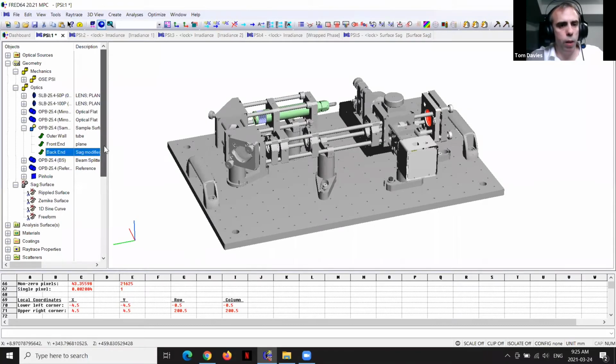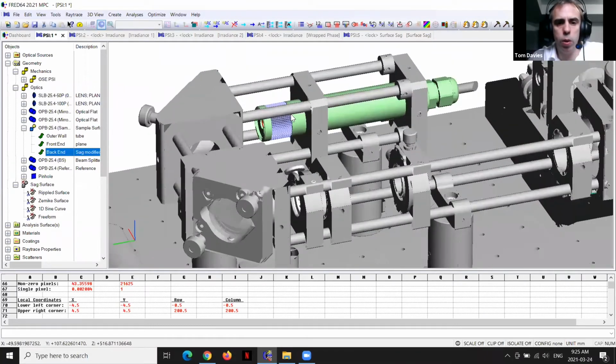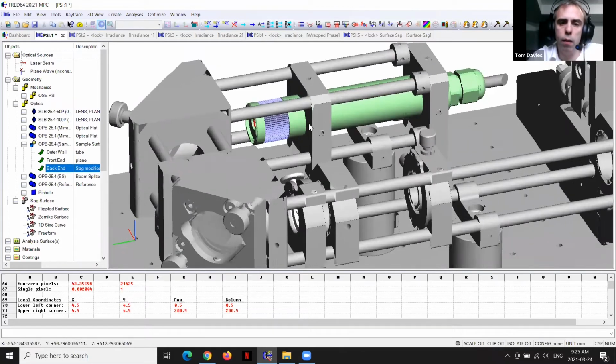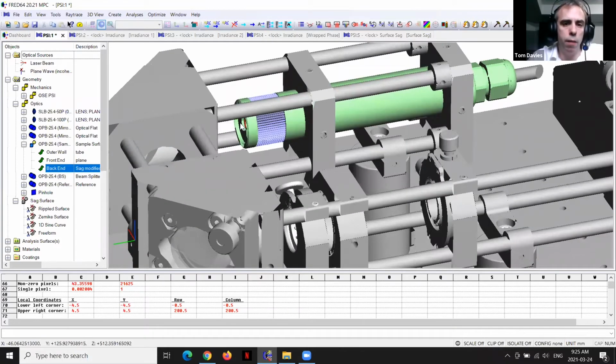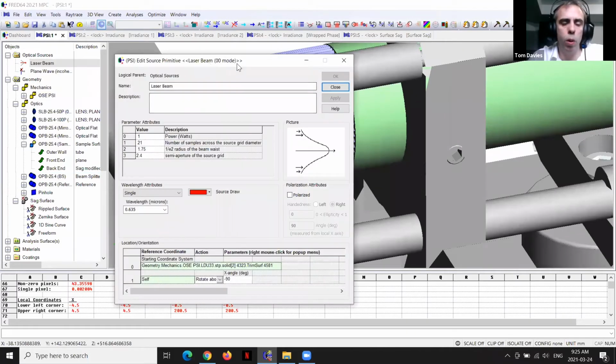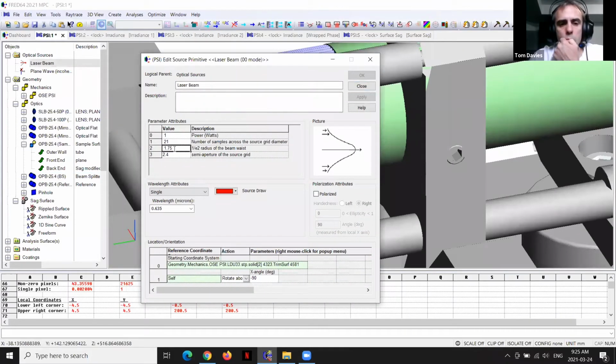I should also point out, if you ever wanted to play around with the source types, just one final thing to mention. In this simple example, obviously we have this laser housing here. But essentially, I just have the optical source right at the output, and I've just defined a simple Gaussian beam source of 1/e² width of 1.75 millimeters. And of course, this could be changed depending on what source type you want to play with. And again, that might be an option you want to optimize.